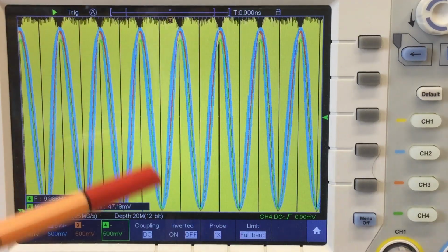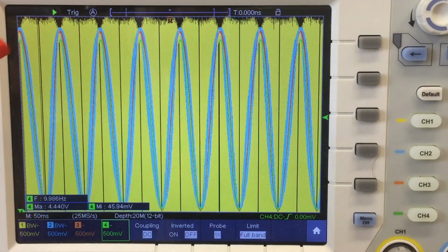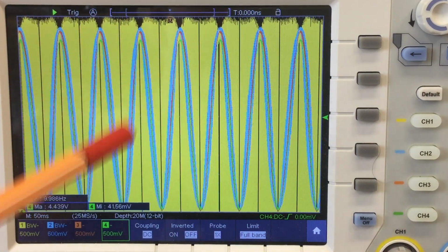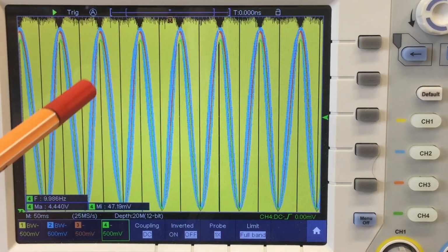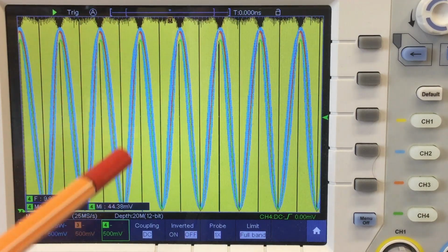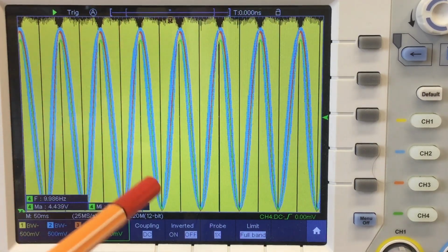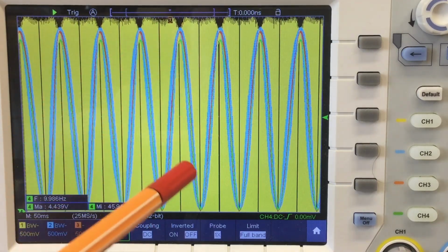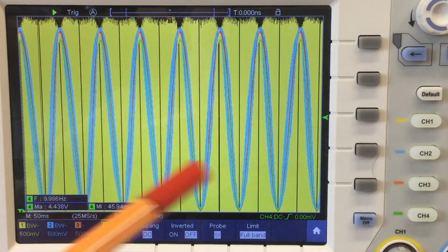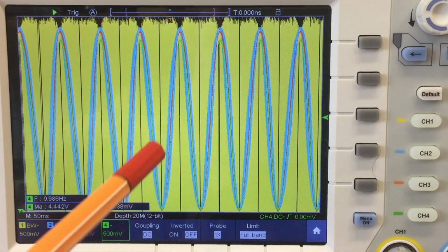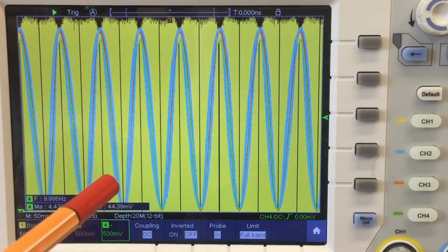And a pretty picture it is. So yellow is our PWM signal. The broad blue strokes here, that's after our first RC element. And you may be able to spot these not as broad reddish strokes. That's our channel 3 after the second RC element. And the output of our filter is that thin green line here.